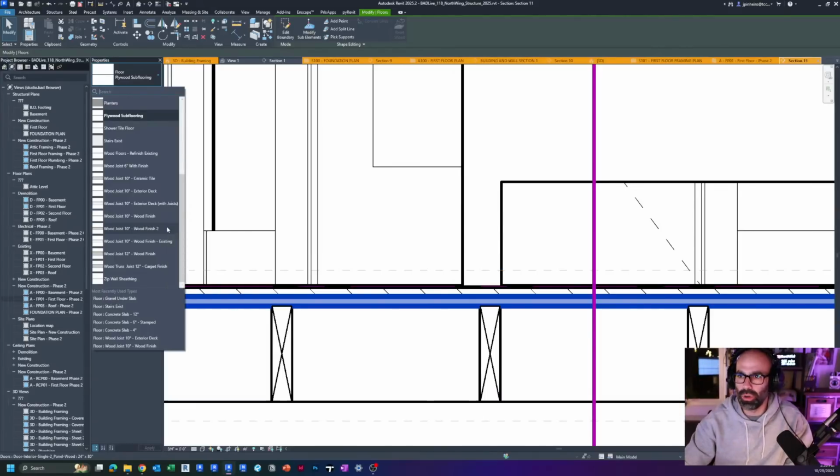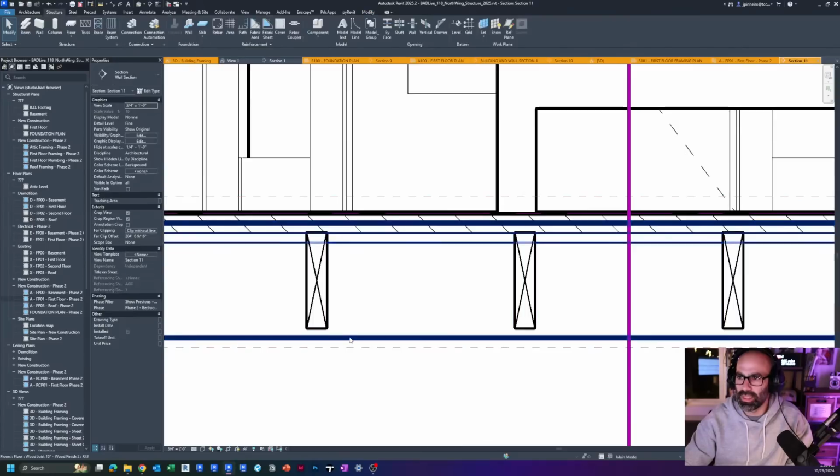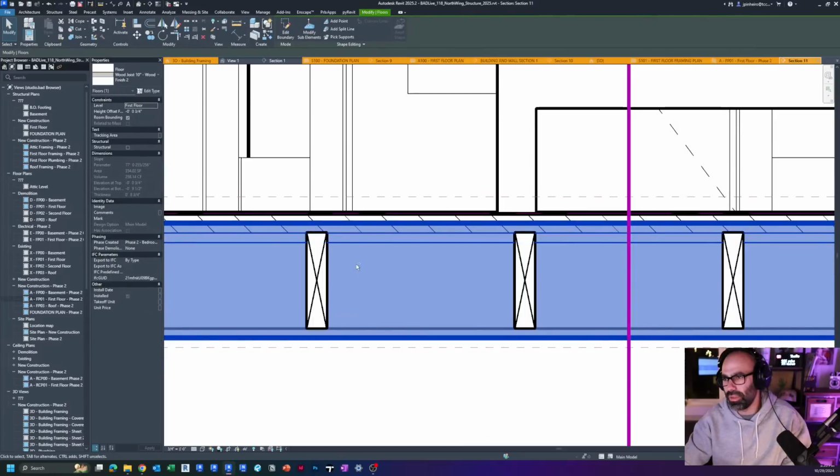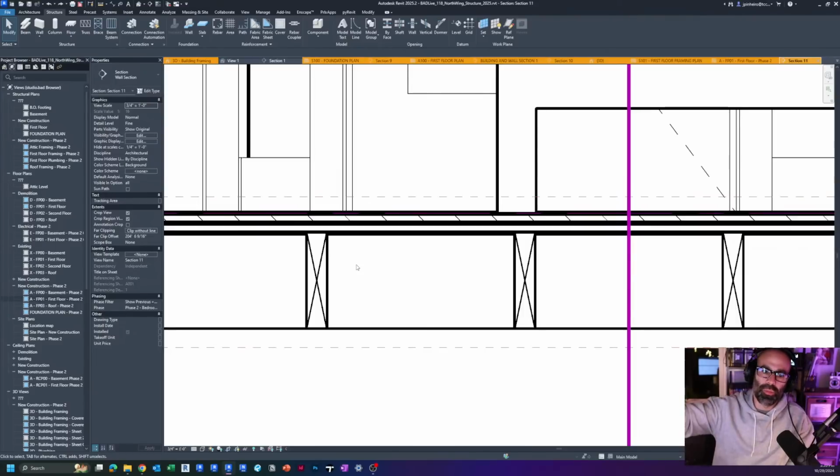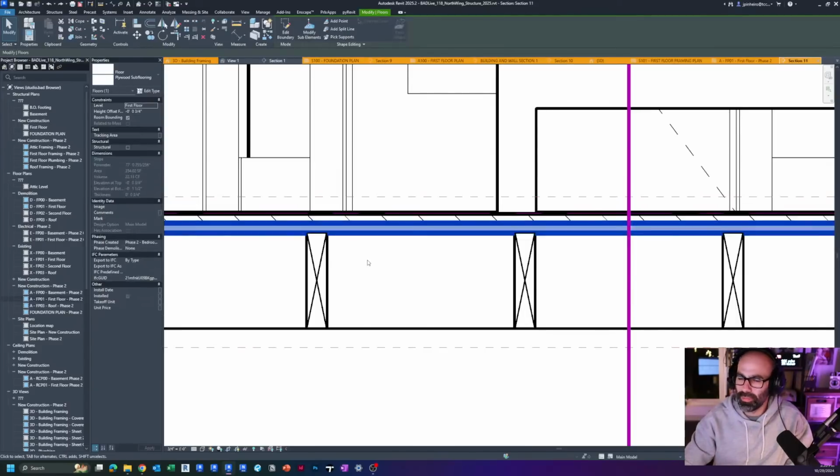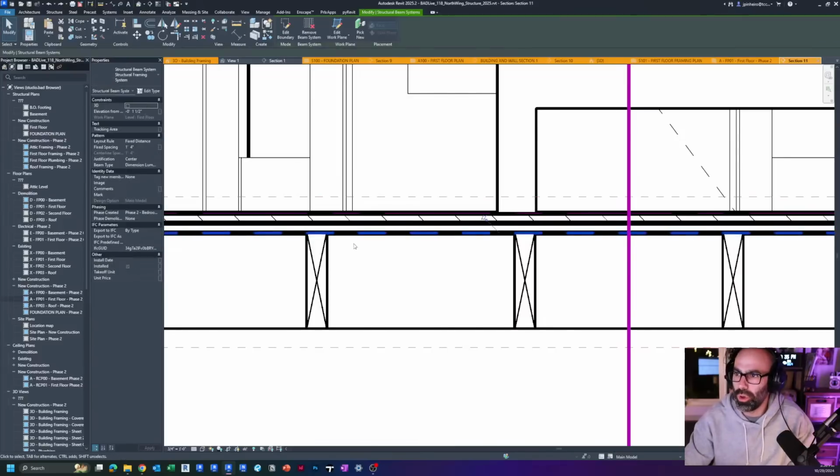Which is your typical, if I click this, it's got the floor, it's got the subfloor, it's got everything in there. Before I build my beams, I transition to a subfloor and flooring model, where I have two different floors. Sometimes it's the same, but usually because this has a bathroom and wood flooring and stuff, I actually keep it separate. And then from there, you can either host your beams to your beam system to your level, or once